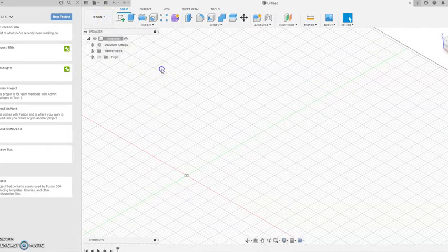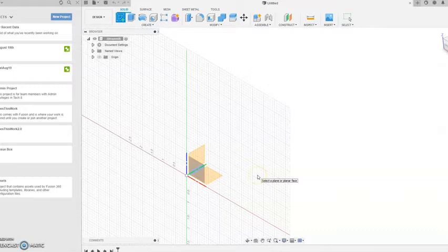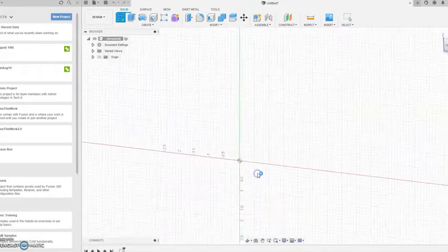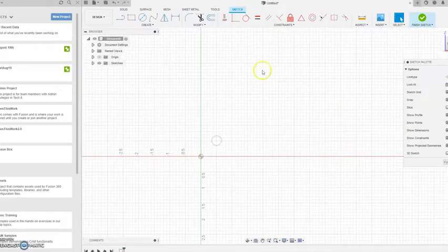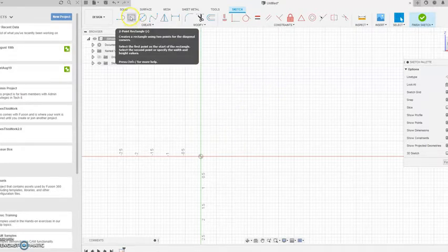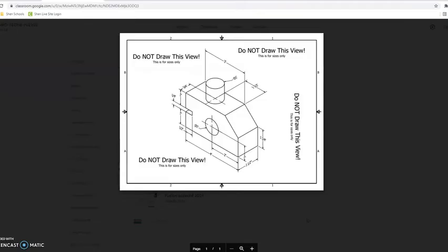We're going to stick with design, and we always start with a two-dimensional sketch on this plane. So you want the vertical up and down plane. You also want to be in the top right corner, which is positive numbers. So I simply clicked once. Then I'm going to use a 2-point rectangle and create the entire area that I will be cutting from and adding onto.